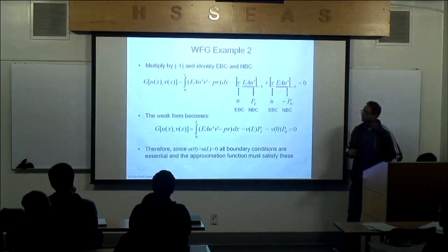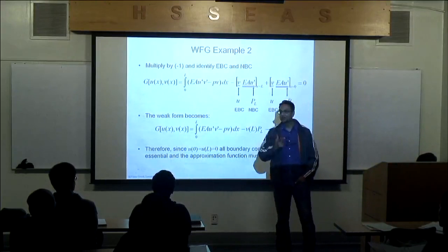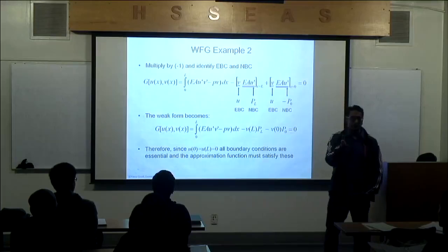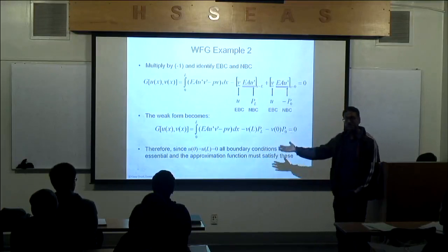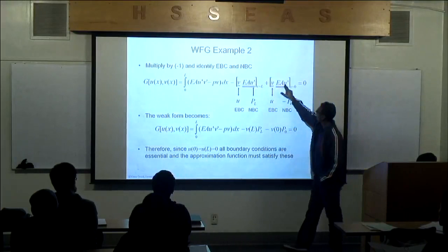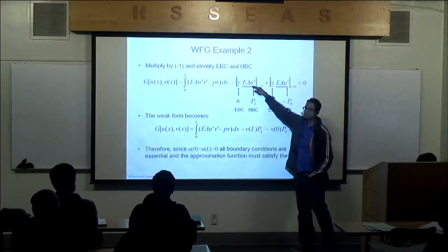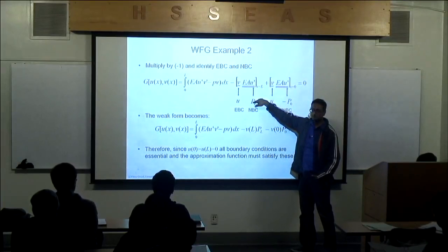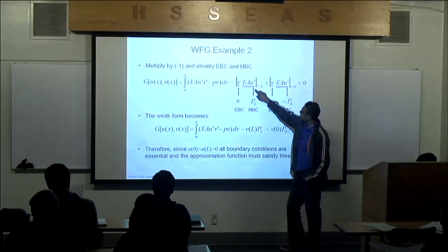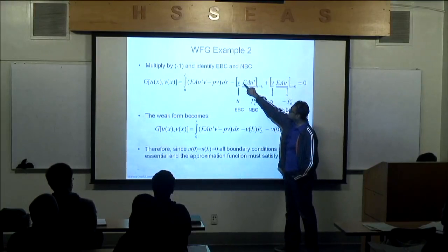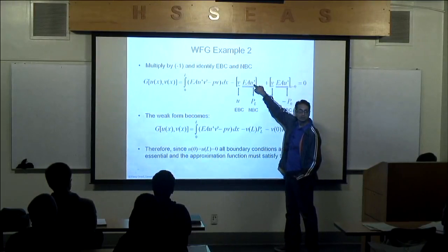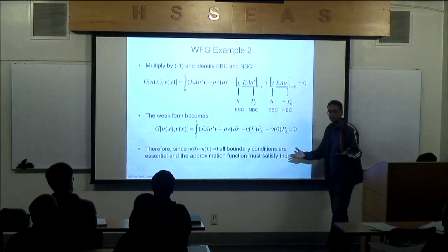In this example, I want you to notice also something really cool. Again, I start with a differential equation, and now I weaken the continuity requirements, and it turns out that these EAU primes have physical meaning. Isn't that what we discussed? This EAU prime is the load at the end, P? If you don't remember, EAU prime is stress, isn't it? U prime is strain, right? What is E times strain? Stress. What is stress times area? Load. Doesn't it work out? It works out.